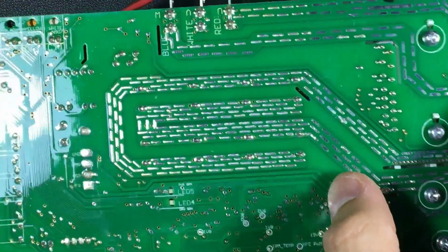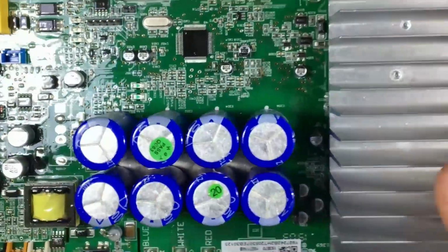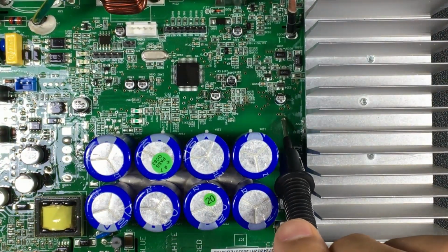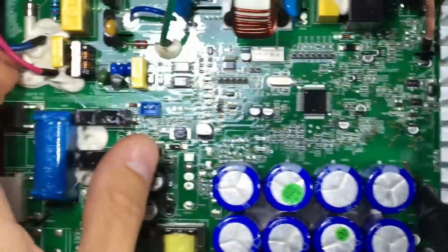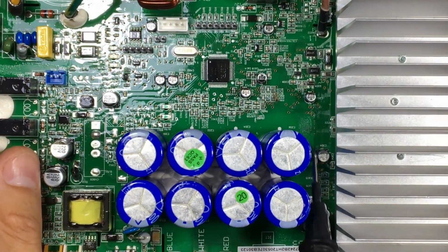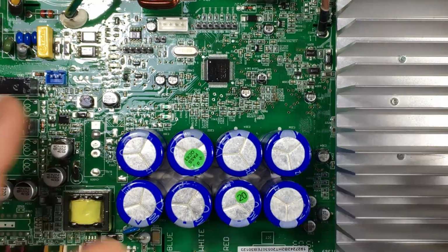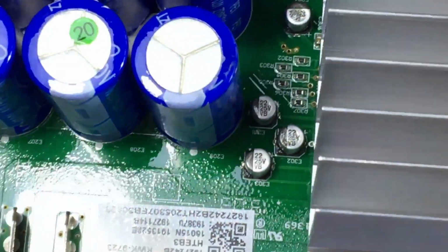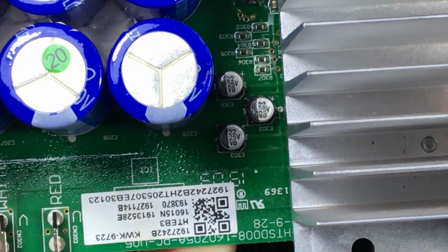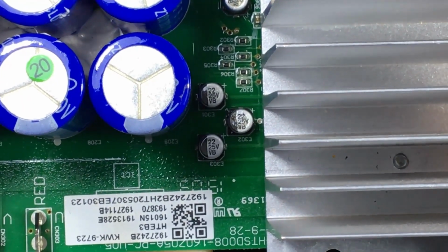Now we are going to the other side. Arrived at this point, in this area. Let's see if we can put a little more light. What is done now is to go from here to these points that feed the capacitors. These capacitors that we are seeing here are responsible for maintaining the 15 volts to power the IGBTs. These are the capacitors that maintain those constant 15 volts that will be injected into each IGBT as appropriate.